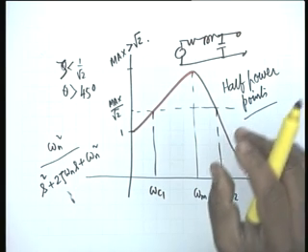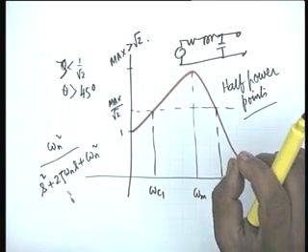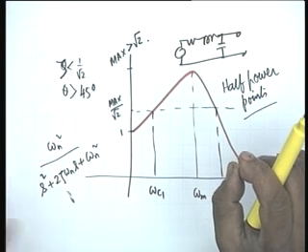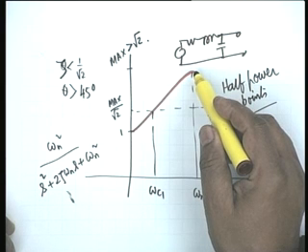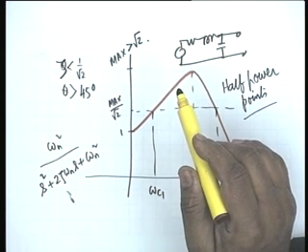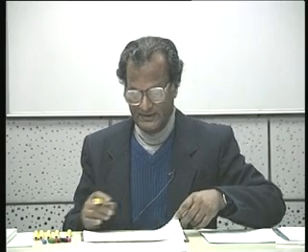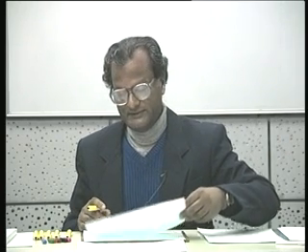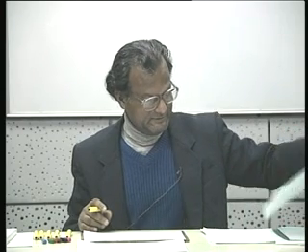If the voltage is taken from the inductor or the resistor, whenever there is a peak, there shall occur 2 cutoff frequencies. But here, 2 cutoff frequencies arise only when the maximum is greater than root 2, not otherwise. If the maximum is less than root 2, then only 1 cutoff. It is of interest to find out where these cutoff frequencies occur, and this can be done by a graphical construction like this.